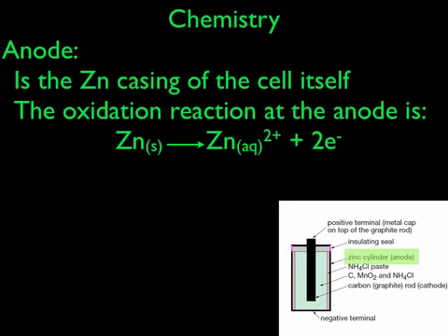You're familiar in seeing that zinc has a relatively high reactivity, which means that it loses electrons quite readily. It will oxidize spontaneously in air. It's not a violent oxidation, but it happens steadily as it loses electrons and forms zinc oxide. So it's a good, cheap, readily available product to use as an anode. Therefore, the whole battery, the outer casing, is actually made of zinc. And with some insulating seals that you can see highlighted in pink, bottom right of screen, the zinc casing is surrounding the entire cell, which makes it robust and sealed.